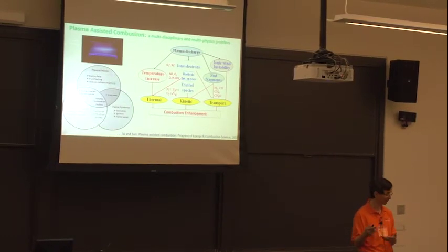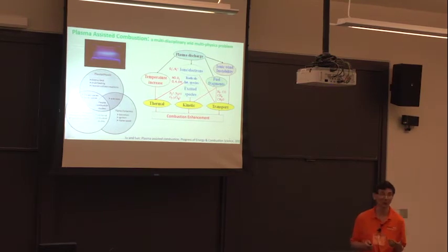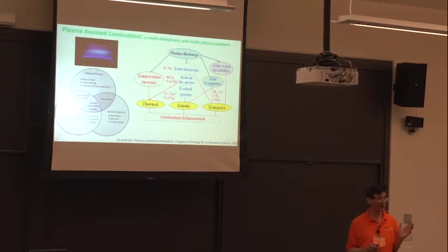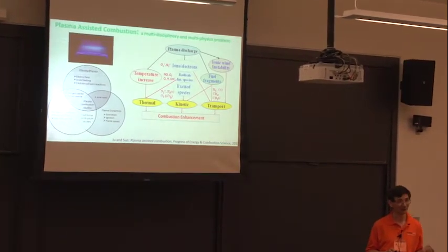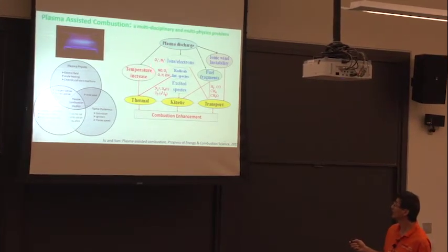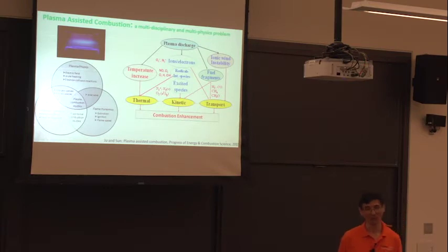How does combustion theory explain that? Really, the thing that the Air Force has been funding us for quite a long time is to try to understand what the reaction pathways are, which reaction is really dominant in terms of the chemistry effect by plasma. For example, with the plasma, you can generate ions, radicals, intermediate species, and electronic and vibrational species. How much will these affect the elementary kinetics? That is really something we want to address in research, and we finally discuss it in this lecture.